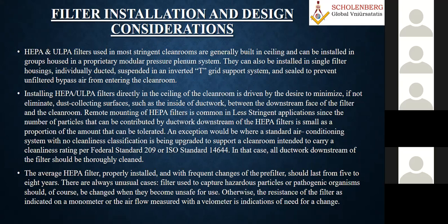Okay, and then come to the installation during the design. How do these types of filters have to be installed? That is a general truth: you know that HEPA and ULPA filters have to be installed always in the ceiling, directly on the ceiling in the clean room, driven by the desire to minimize the dust collecting surfaces, such as the inside of the ductwork downstream of the face of the filter. So remote mounting of filters is also common nowadays.